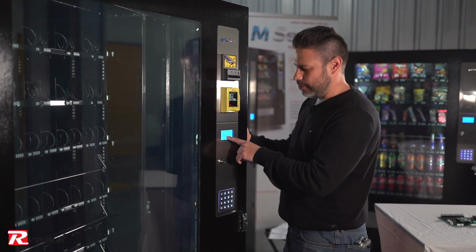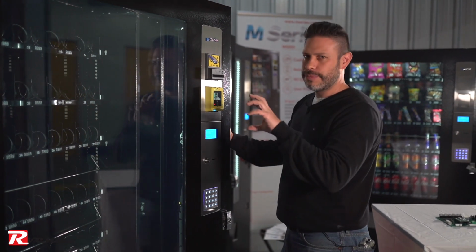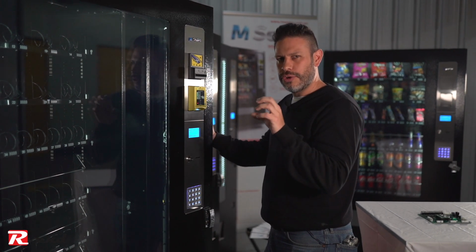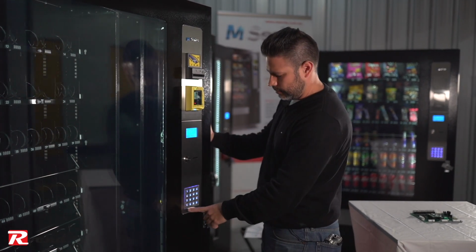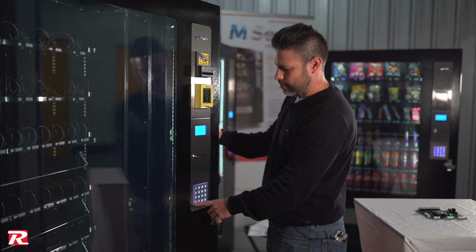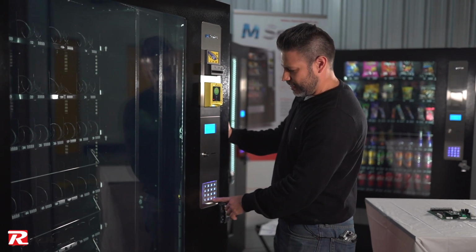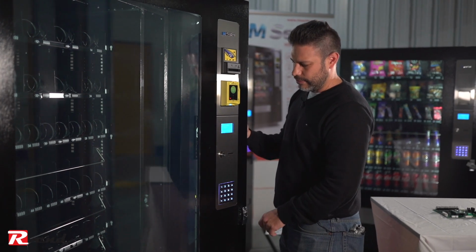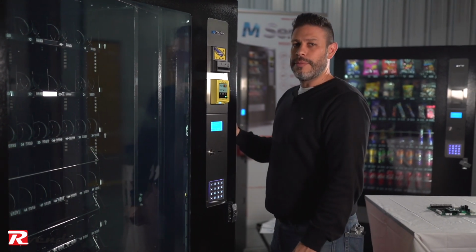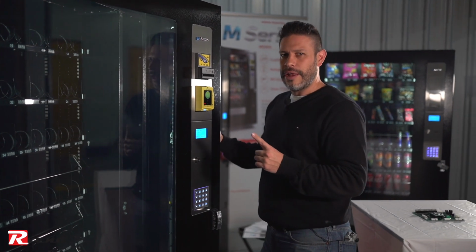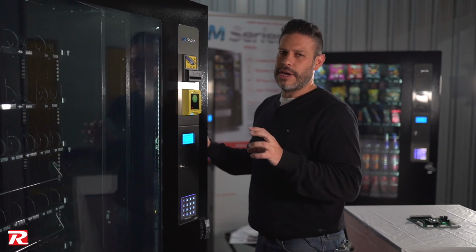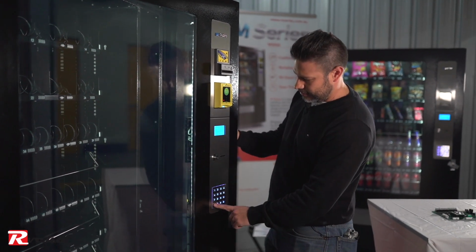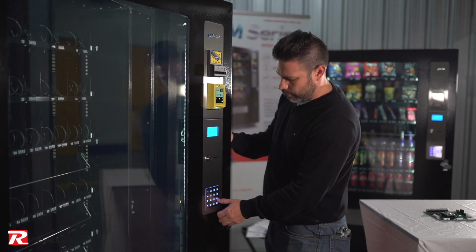The drop option will turn the spiral a little bit, just a quarter of a turn, just to try to ensure that the product is not jammed. If you want to change that one to drop, you just press hash to enter. At this point, the motor will turn just once, and then quarter turns every time the product is not detected. All right. If we want to go back, we press C again.